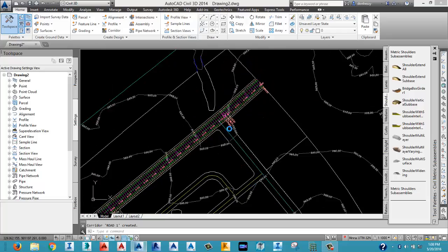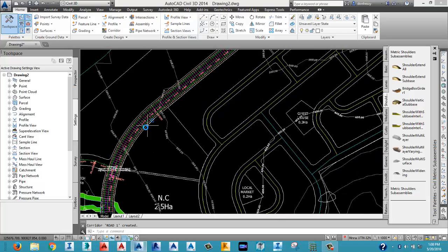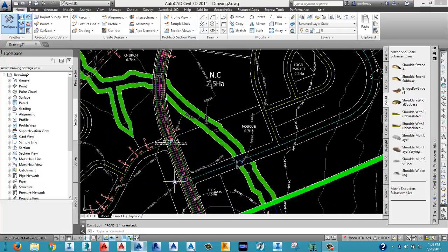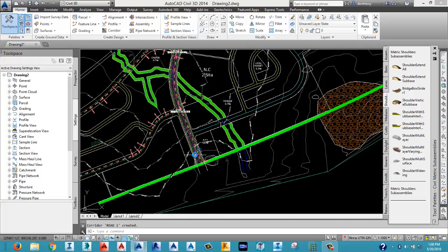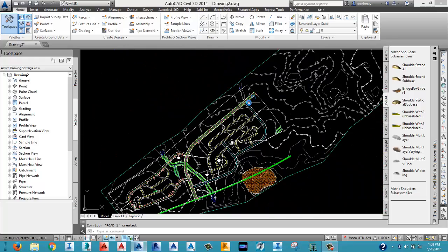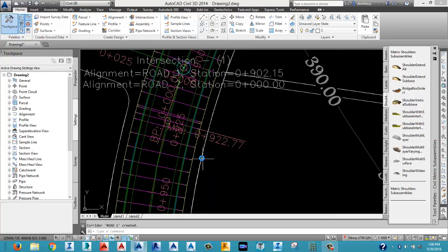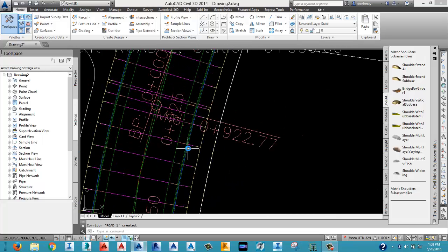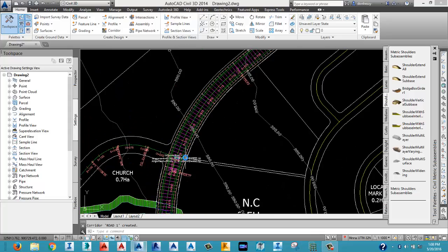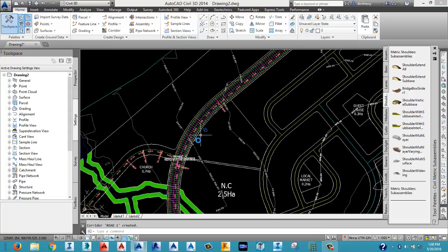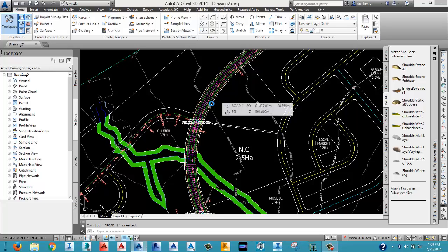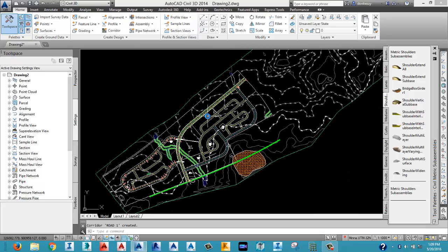So you can now check what you have in your plan view. You can check the corridor. The reason why you have it at 5 meters is that, assuming you had it at a wider interval, at this curve you might not see a smooth transition curve at this bend. You might have your corridor modeled in a very nasty way. So it's always good to have a closer range of your assembly, so that you can have smooth curves and bends and so on.